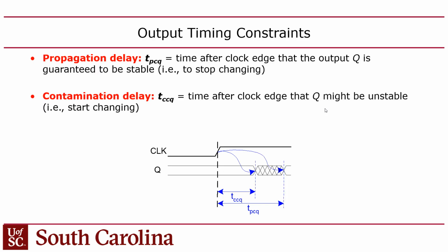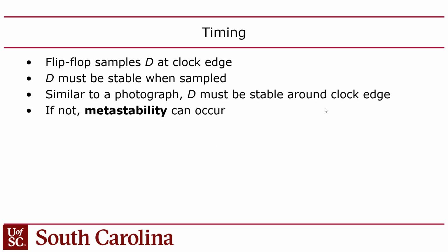It's a constant. These are constants, right? Now, likewise, even on an ASIC design, generally when you design on an ASIC, you design with what's called a standard cell library. So you will synthesize your designs onto an ASIC. The flip-flop will be part of the standard cell library. So again, unless you want to create your own optimized flip-flops, which hardly anyone does, because you go to TSMC and they will give you the standard cell library that you will feed into your synthesizer. And so again, even on an ASIC, these are basically constants that you have to deal with.